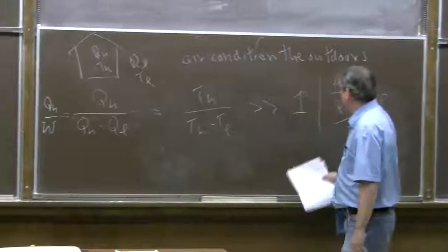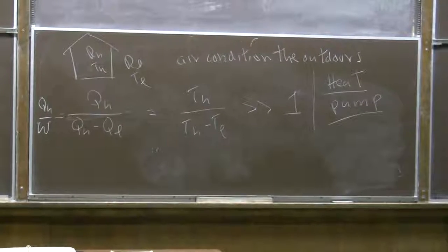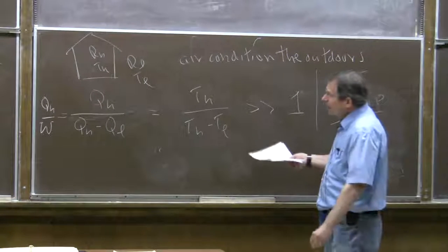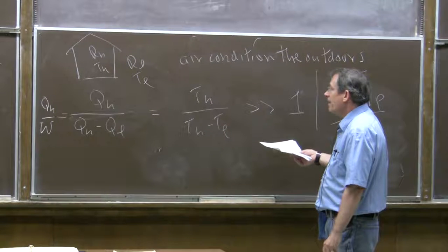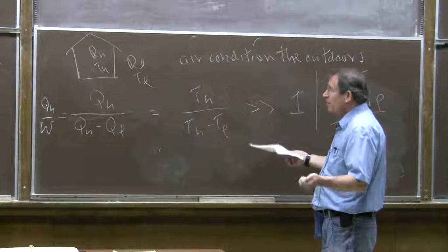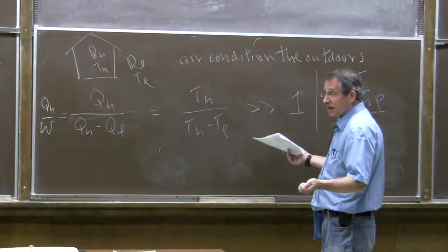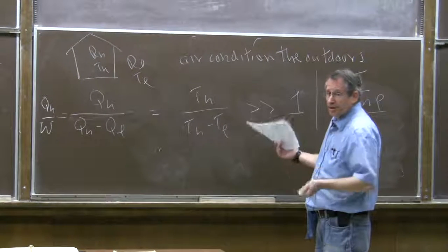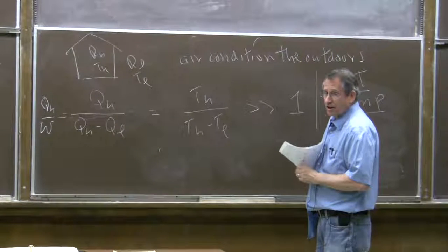So a heat pump, from the point of view of ideal thermodynamic efficiency, makes a lot more sense than direct heating. But there are various engineering details which we don't usually worry about as physicists, which make the heat pump not necessarily the preferred choice. Heat pumps are kind of expensive. Although some modern houses have air conditioning systems which can be run in reverse and act as heat pumps. Part of the reason it's not necessarily economically the best option is that it's cheaper to burn natural gas like I do than to use up electricity like my friend does, running his air conditioner backwards.